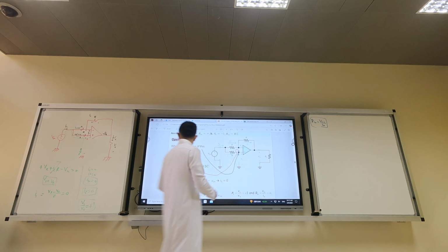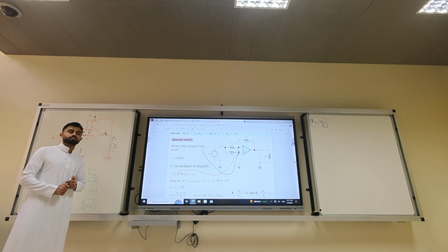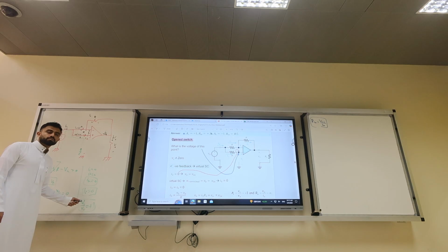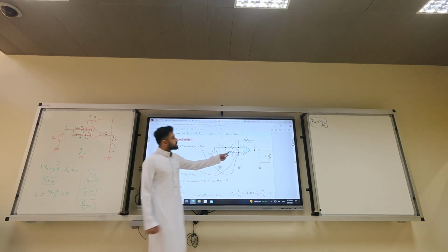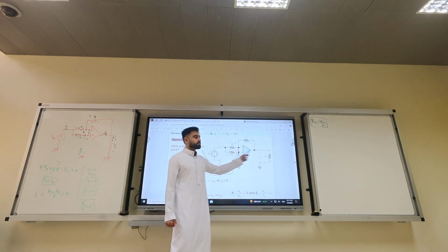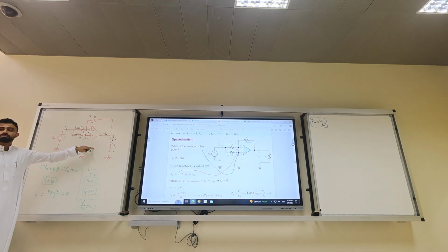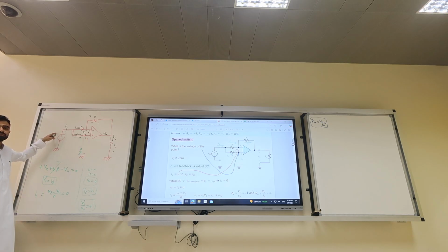Does the gain, which is plus 1, rely on R load? Is there R load in the gain equation? It means it's like car speakers. It can drive whatever output, and it gets Ix, which is this one, from the supply. And this Ix is what generates the output, and it mimics the input signal.